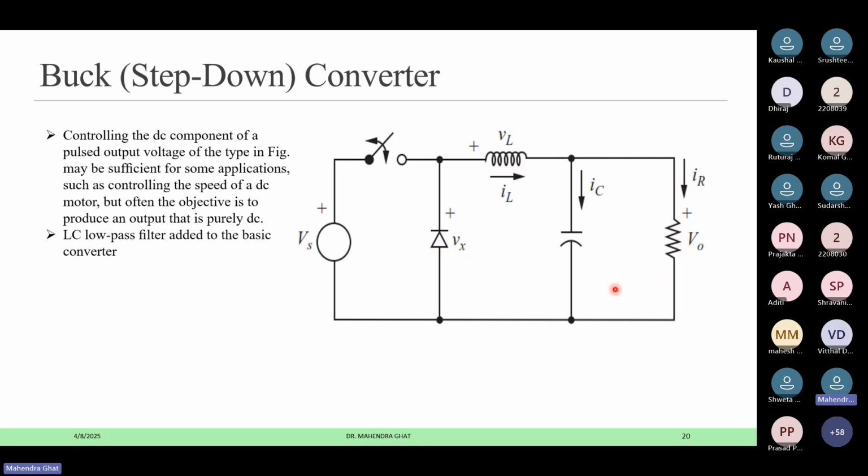To get this in a buck converter, it uses one controlled switch. It can be either an IGBT or a MOSFET. It can use a thyristor, but if we are using a thyristor, there is no turn-off capability. You already studied the thyristor. You can switch on the thyristor, and we have the DC, so it will always be in forward bias. You can switch on the thyristor, but you cannot get natural commutation for it. You require forced commutation to turn off the thyristor.